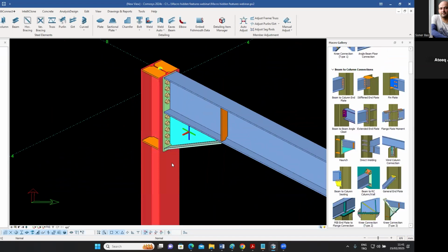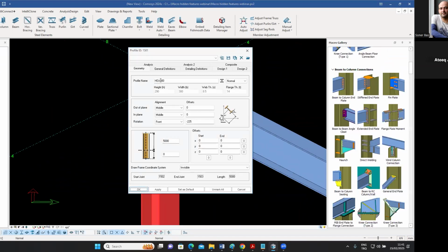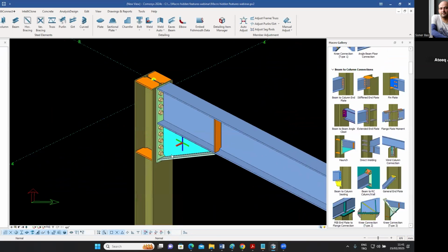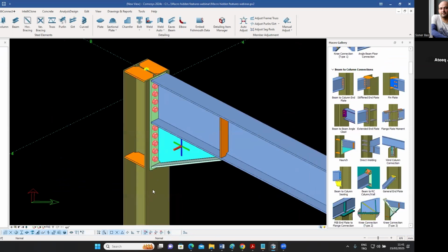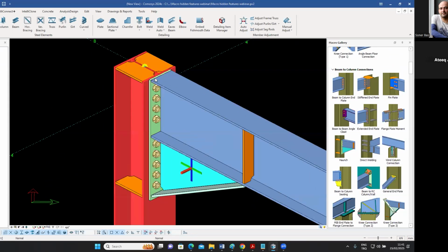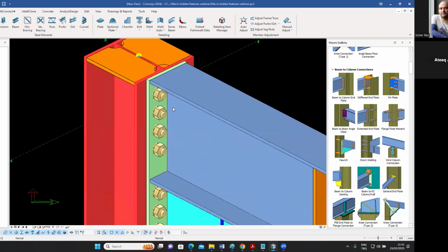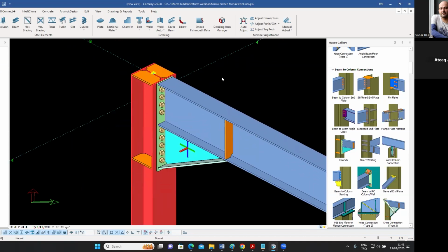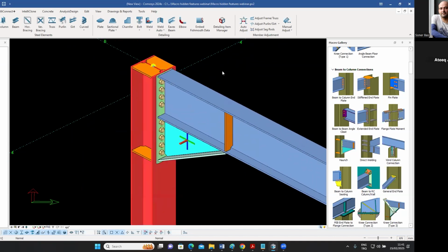And this one over here, this column is HEA 300. Now, once again, the standard recommends that the bolts which are placed on the flanges of sections need to be at a certain line. And this line is well defined by the standards. It's not the typical gauge. These are also gauge lines, but different from angles. But they're different for every single section.